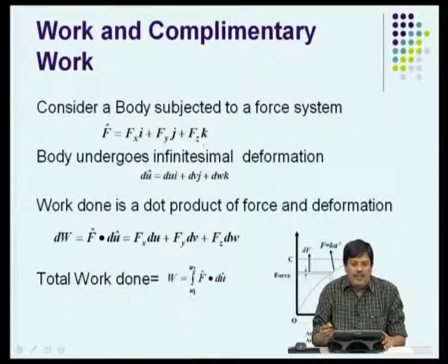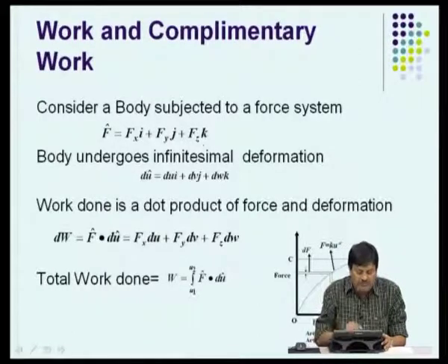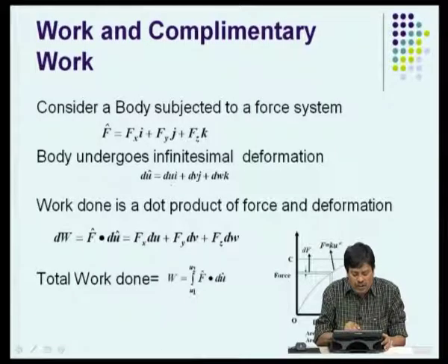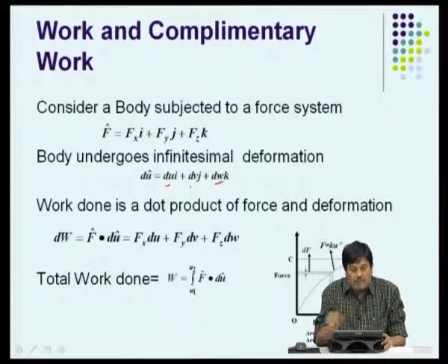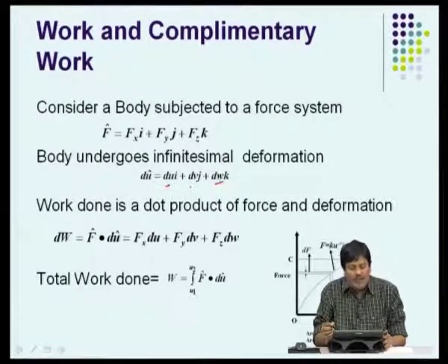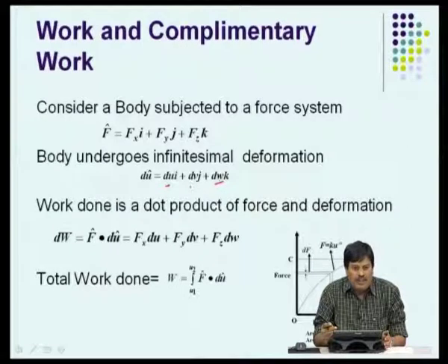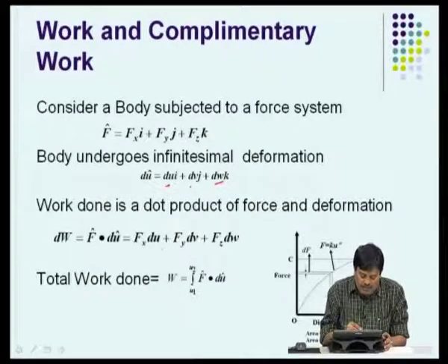If the body undergoes small deformation, which I call du, which has 3 components again, u in x direction, v in y direction and w in z direction, the work done is nothing but force into displacement. So, in terms of vectors, it is a dot product of f into du, which is given by this.